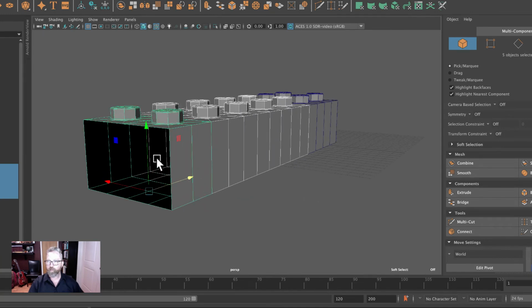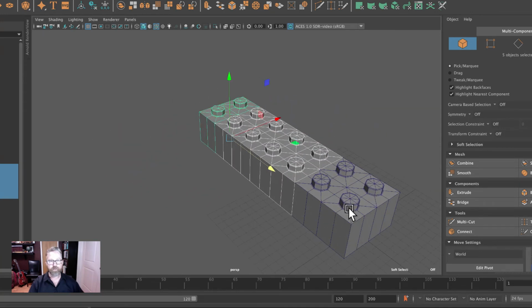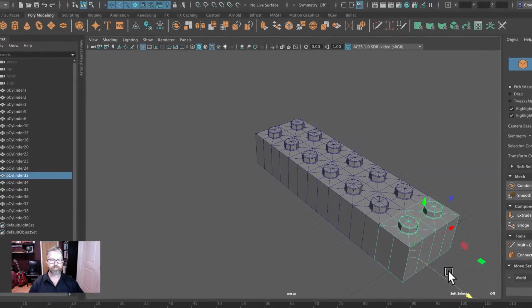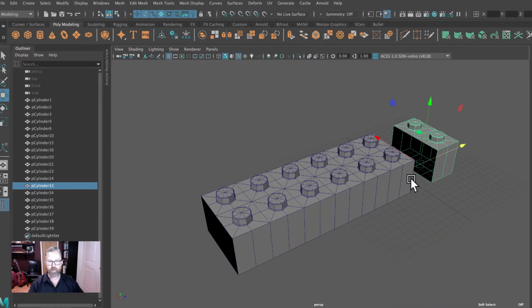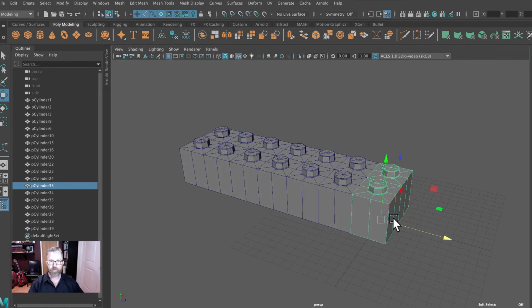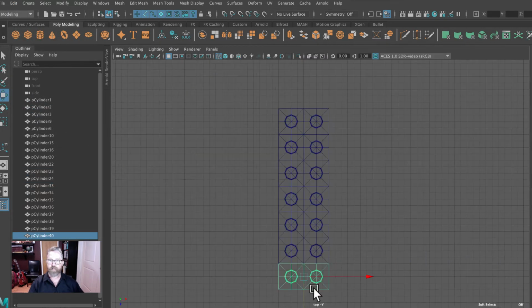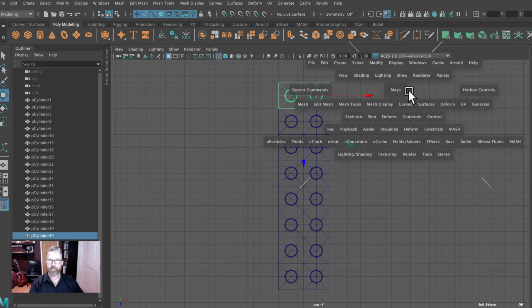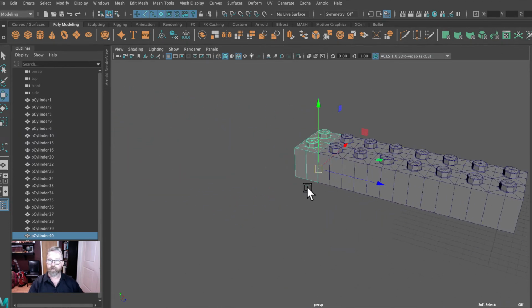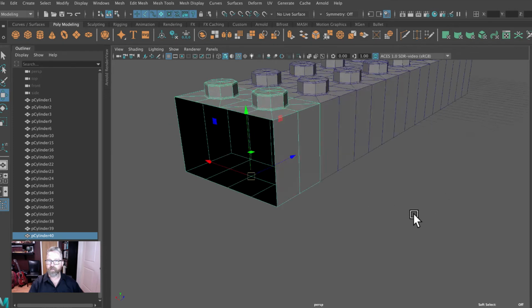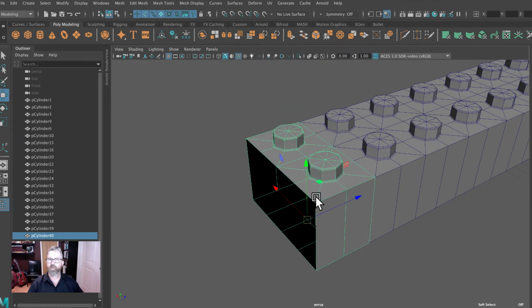Now we have this open piece here, and so let's just duplicate our original, that has these end faces already deleted. So we'll duplicate this, edit, duplicate, and let's slide it down the line in the top view. So we've got a new duplicate. We'll just grid snap this down here, and then we have to turn it around. The deleted set of faces are on the wrong side. So we need to rotate this 180 on the Y.